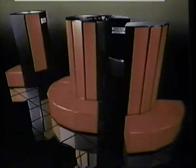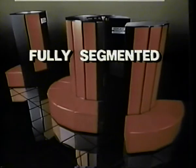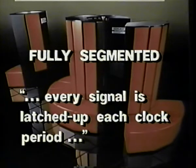The Cray XMP computer is a fully segmented machine. Fully segmented means that every signal in the machine is latched up each clock period. Since the XMP is fully segmented, a new operand can be issued every clock period.